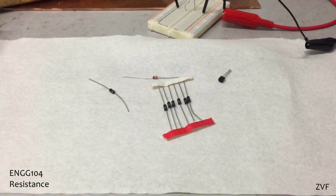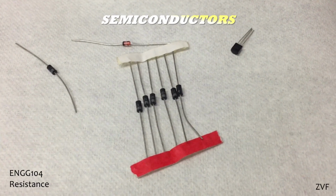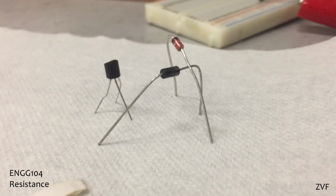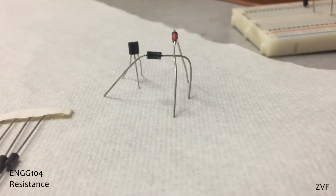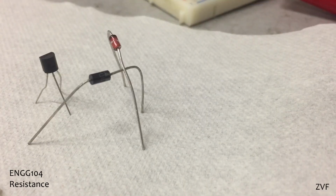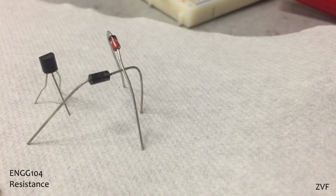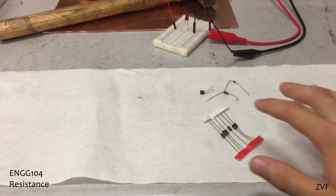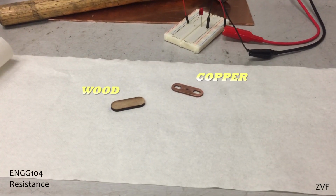In other materials, like semiconductors, a negative temperature coefficient may emerge, whereby resistance decreases with an increase in temperature. The additional thermal energy frees electrons so that they may conduct, unlike in a conductor where a sea of free conducting electrons already persists. This disparity in physical structure alludes to the material dependence of resistance.